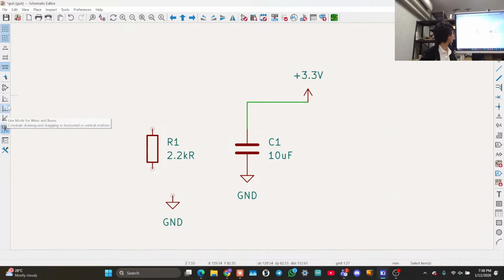Okay, so this is where your wire routing starts, this is where your line mode matters, okay? So by default, most schematics are just gonna be horizontal and vertical because it's clean and easy to read. But if for some reason you feel a need to be special, then you can like do stuff like this, you know? Which, like, why would you do that? Why? Like, how is anyone else going to read your work now, you know? Why have you wanted your friend to check your work before you spend money on the PCB? So like, just use this and it's way better, okay? There's also this mode where like you can do this, so it's like 45 degrees horizontal and vertical. Again, why? This is a graphical representation of your circuit. The shape of the wires does not matter, okay? So just do the thing which is the cleanest, which is vertical and horizontal, like that, okay?